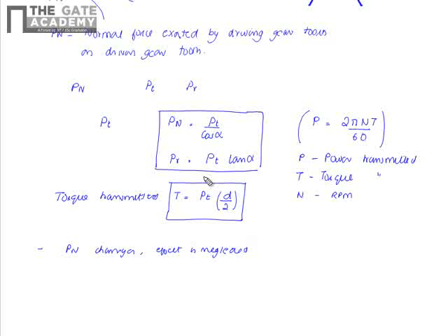And another basic assumption is that during mating only one pair of teeth takes the entire load. That is a major assumption which we take here. That is, only one tooth is in contact with the other. In reality, at times there are two pairs which are simultaneously in contact and they share the load. And this aspect is not considered in this analysis.